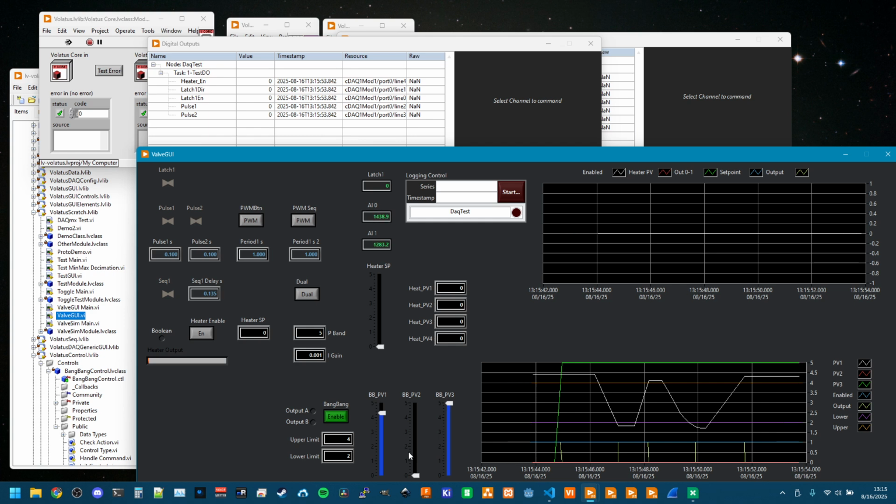So that's an easy way. I don't have to make the bang bang more complicated and handle multiple outputs. There is a configurable component for doing that logic of mirroring that command to multiple outputs. I could probably end up doing something similar with some kind of input logic where something needs to get commands from multiple sources or verify the state of multiple sources to generate an output value. But again, that's the whole idea with this: create these small building blocks that can be combined and chained to get the higher level, more complex system behavior.